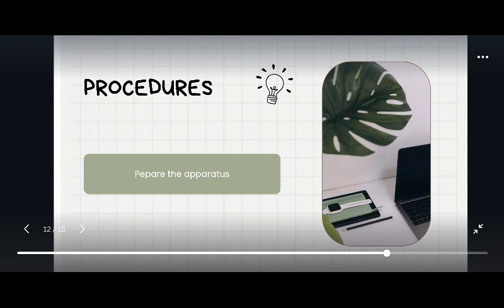First, students need to prepare the apparatus. Take 200 grams of the soil that passed the No. 40 sieve and place it onto the glass plate. Thoroughly mix the soil with a small amount of distilled water until it appears as a smooth uniform paste. Cover the mixture with cellophane to prevent moisture from escaping. Label and weigh 3 empty moisture cans.